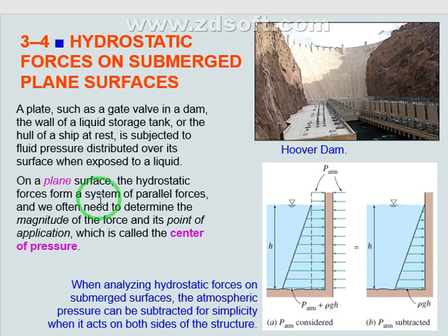Now I need to apply the concept of hydrostatic forces on submerged planes. As you know, we can have any plane inside water, inside any liquid. We have some formulas to calculate the pressure. It's very simple, very easy. It depends on this concept: rho g h. This is the gauge pressure; for the total pressure, we must add P atmosphere. So I need to know the liquid, then I know rho, then I calculate the depth, finish, done. This is the concept.